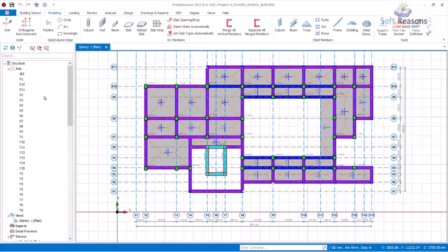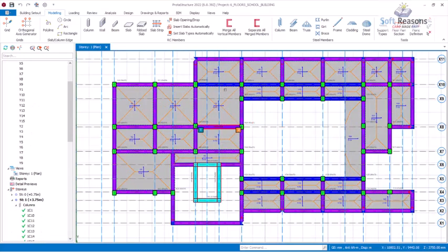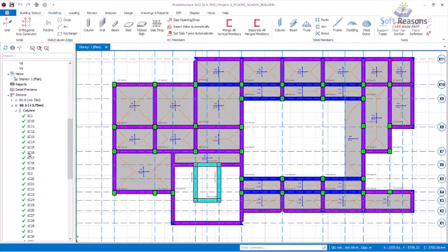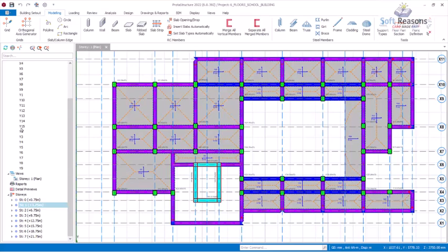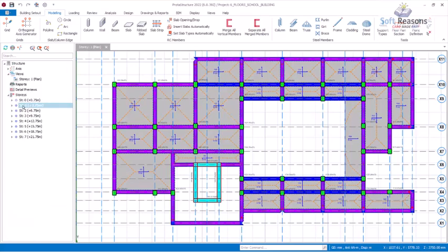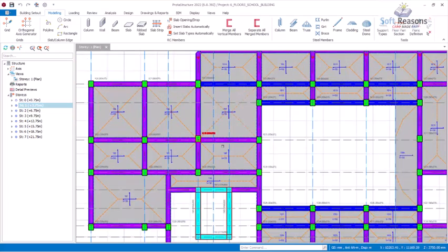The lowest structural floor of a building carries the largest sections of reinforced concrete column, just like we have it here. Over here we have ST1. Let me minimize all of this. This ST1, which is Storey one, should carry the largest sections of reinforced concrete column compared to ST2 up to ST7. If for instance you have ST1 to be 300 by 300 and ST2 to be 400 by 400, that is a very big error in the course of structural design.